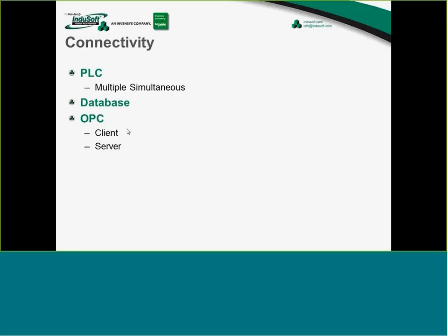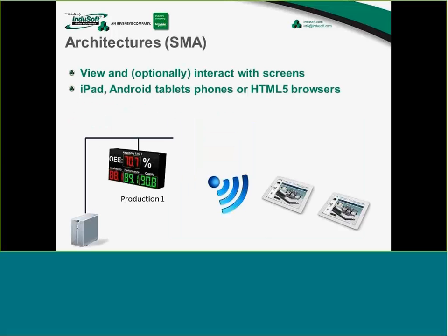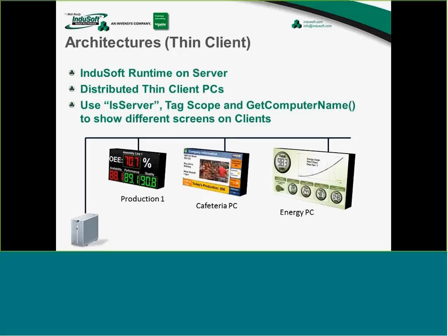So talking a little bit about connectivity, some really interesting things that I've seen is using multiple PLCs. And if I go back to an application that's maybe like this diagram, what might be interesting is, especially if you have these large screen monitors distributed throughout the plant, and maybe they're in different sections of the plant, you might have one section for production getting information from one brand of PLC, and a different application in a different part of the plant, even though they're driven from the same server, maybe that's talking to a different type of PLC or a different protocol.